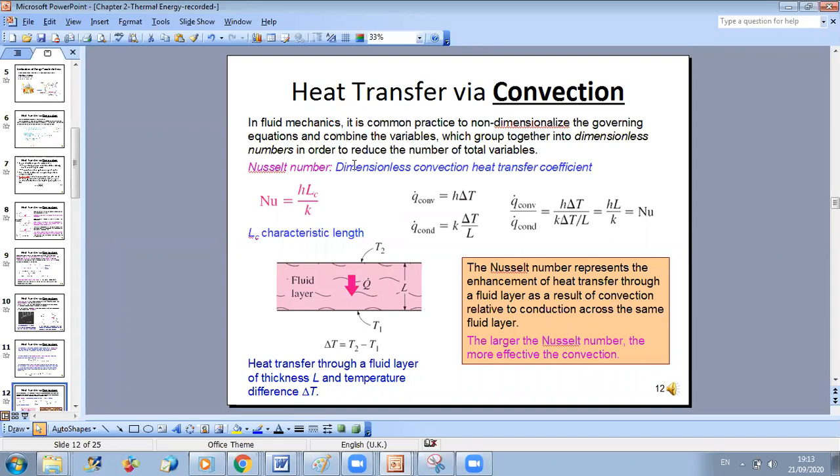So whenever you do an experiment and express your empirical relation in terms of dimensionless terms, your empirical relation will involve a relation between, let's say, the Nusselt and Reynolds numbers, which we will define later. When you find an empirical relation between these numbers, your result can be extrapolated to any other case. This is the importance of dimensionless numbers. Now, how do we come up with dimensionless numbers? A dimensionless number always has a physical meaning. So let's go first with the Nusselt number.